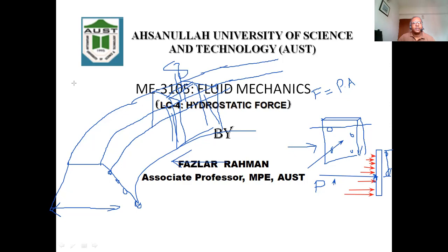So this plate, if you think of it another way, is a cantilever beam, with this pressure working. Let me take the arrow right over here. You have support on both sides. So this is the support. Then if you know this force and its location, then from the geometry and the location of this pressure, you can figure out these two reaction forces, this one and this one. Then you can design the sluice gate.